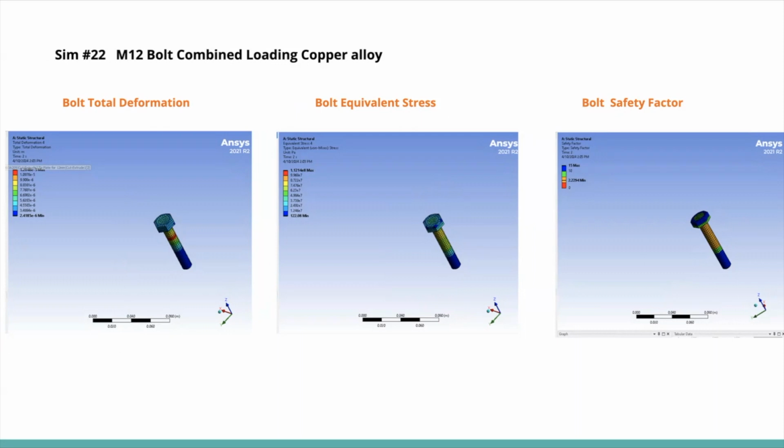So that would be a reason as to why we should pay attention to what material as well as what bolt size we use for the system. Because if we were to use a smaller bolt, for example, like the M8, having all that pressure placed at that point with such a small diameter of a bolt will break the system and make the system unable to use, or it's deformed at that point. So being able to have a good bolt size is very important.